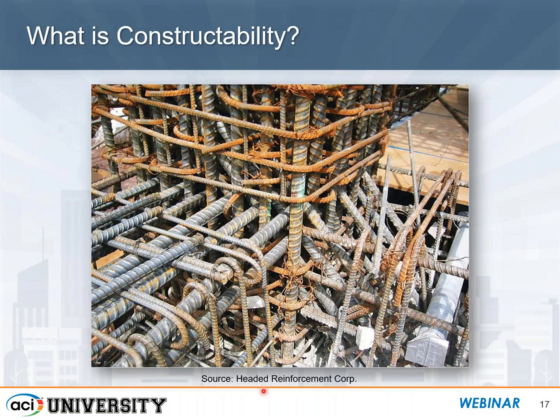The bars are sort of helter-skelter everywhere, and you know, we can't blame the placers for that. If it's going to happen, it usually happens at these beam column joints, and this is where a little implementation of some things prior to construction would have basically eliminated this situation at this particular joint.